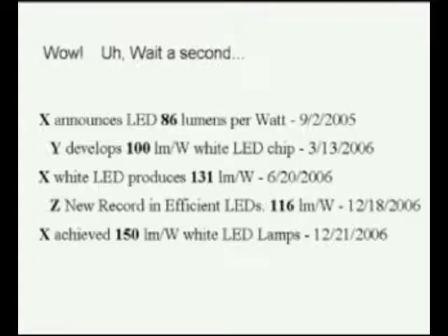25-25 test. This is fine if you're doing a pulse measurement to check the light output or the efficacy at the end of a manufacturing line, but it does not indicate the efficacy that you have in your application, a real lighting application. Because this device has to be put into a package, that package has to be put onto a board, that board has to go into a housing, and there are losses all along the way, to the point where 150 lumens per watt may be reduced to less than half of that when all is said and done under steady state operating conditions.